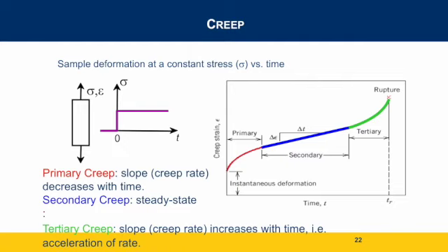The material accommodates to the force. I'm bending the material, and it's supposed to be in its elastic range, so if I let it go, it should bounce back. But if I hold it long enough, the material will start to relax, and when I release it, maybe several hours or days later, the material may not go back. That is basically dissipating the stress inside the material by relaxing the atoms, and that's called creep.